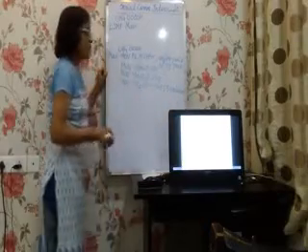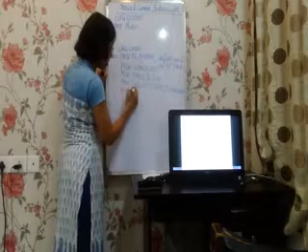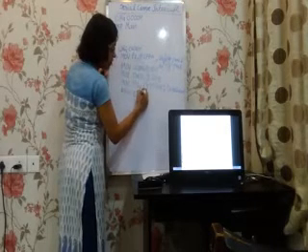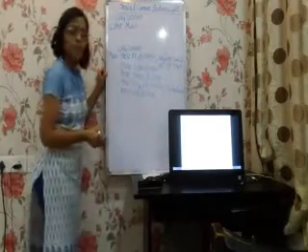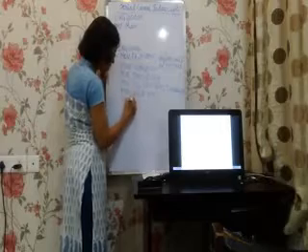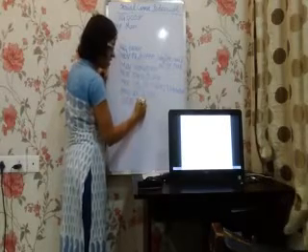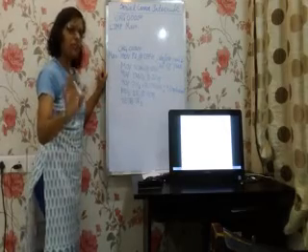This is the prerequisite that we need to do, and we need to configure the IE register. We have already found out the value, it is 90H. So MOV IE, #90H, and start the timer. Once the timer is started, the data transmission or reception, whatever has to be done, will be started automatically.